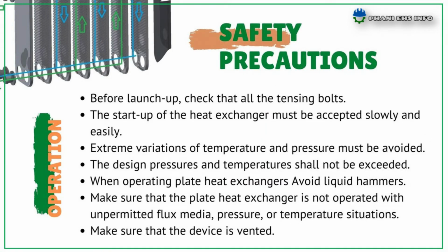Plate heat exchanger safety precautions. Before startup, check that all the tightening bolts are forcefully tightened and that the plate pack has correct measures. The startup of the heat exchanger must be done slowly and easily to avoid any pressure shocks, water hammer, which might damage the equipment or cause leakage. Extreme variations of temperature and pressure must be avoided in order to avoid damages.